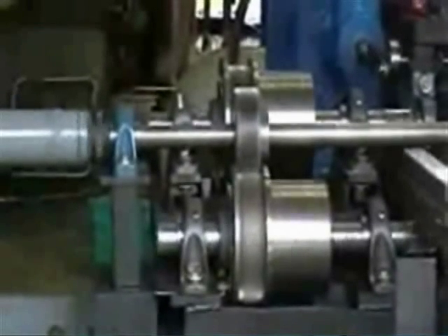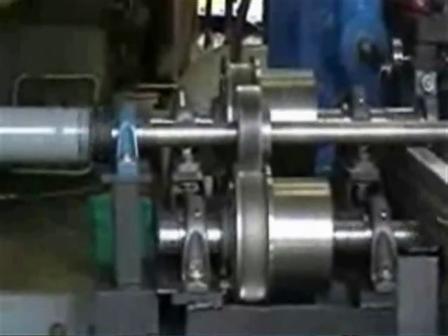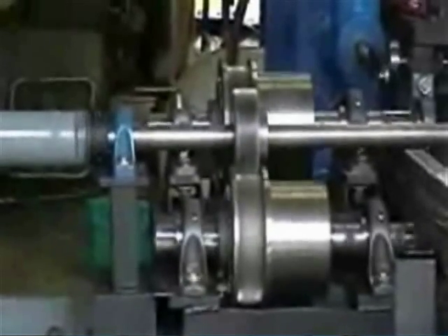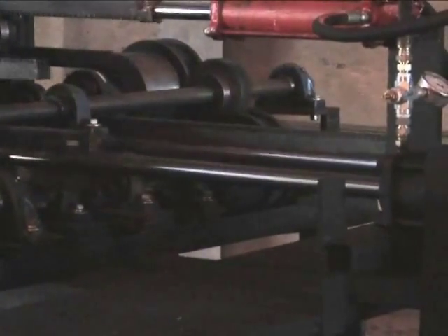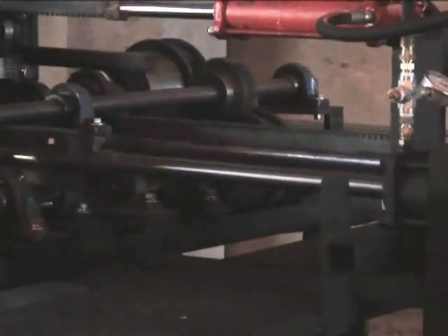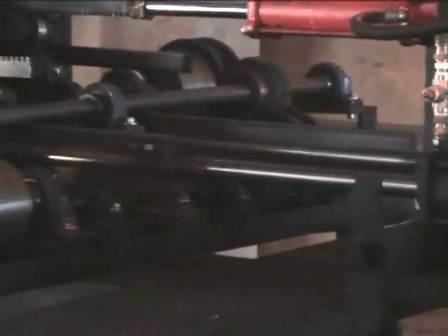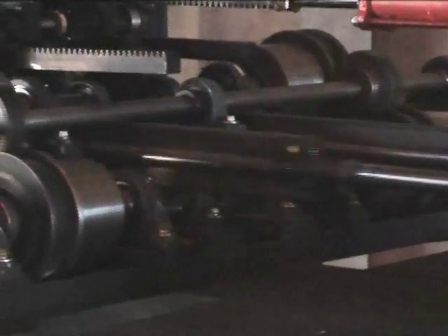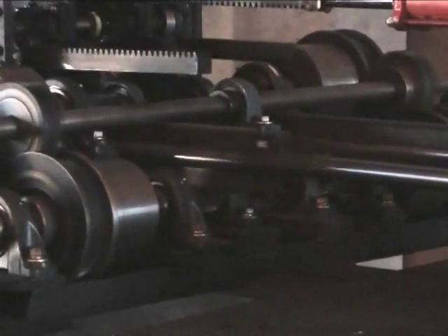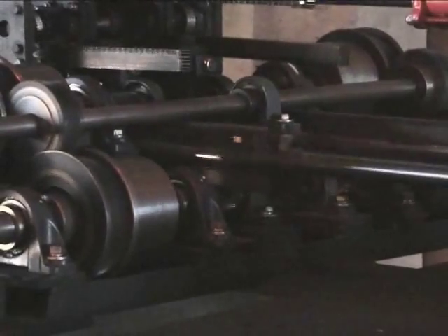An indexing Sprag gear catches in one direction, providing rotation of a shaft, then slips or overruns in the opposite direction, providing incremental rotation of the shaft in only one direction. Our novel Sprag gear transmission uses dual sets of rack and pinion gears in association with two Sprag gears that provide multiple shaft rotations during the outward stroke of the rack bar that is driven by the piston, and an additional multiple rotations of the shaft are gained on the inward stroke of the rack bar. And a perfect 90-degree vector angle is always maintained during its highly efficient operation.